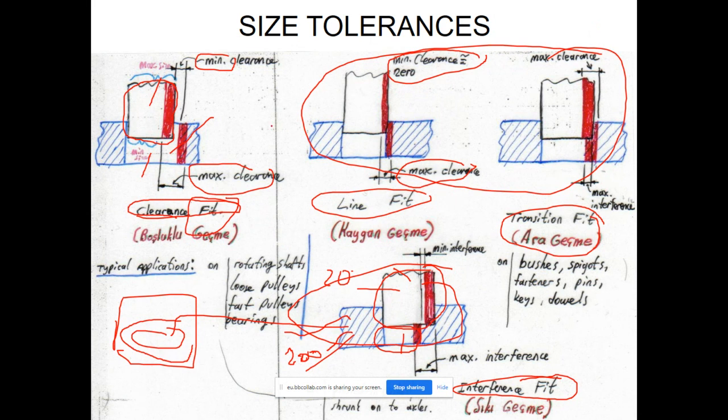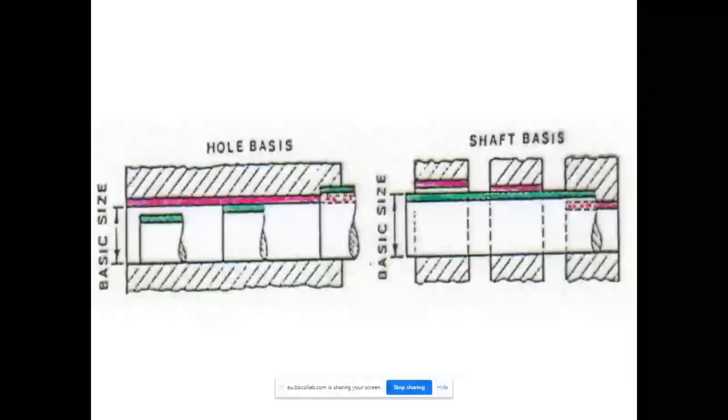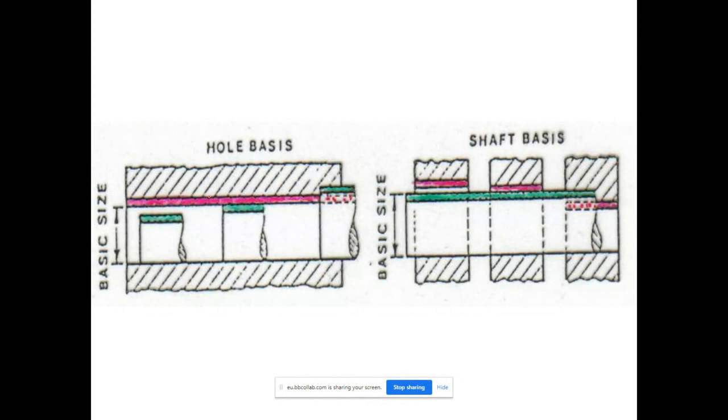The answer is that on the technical drawing for each part, after individually selecting the tolerance grade, we show the specifically selected tolerance grade on the technical drawing of each part so that we can guarantee to have the fitting in the correct order. At this point, I'm going to give an example, but before the example, first address this table.